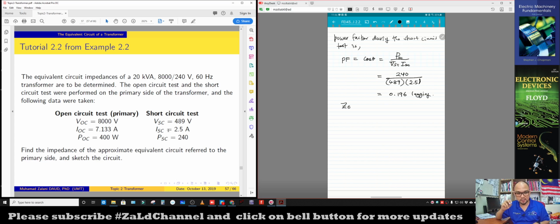Once we get the power factor, we can determine the values of the series impedance ZSE. The series impedance consists of equivalent resistance and equivalent reactance, right? So ZSE we can calculate using VSC divided by ISC, with the angle we have already determined from the power factor. Now just substitute all of the values: 489 of voltage divided by 2.5 of current, and then cosine inverse.